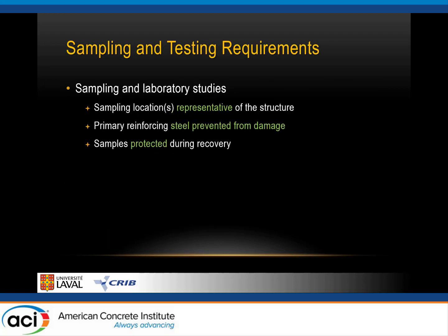So in order to perform these different tests, either NDT tests and lab tests after that, sampling is a very important aspect. When the sampling plan is designed, it's got to be representative of the structure.